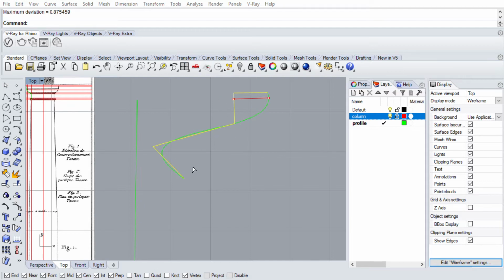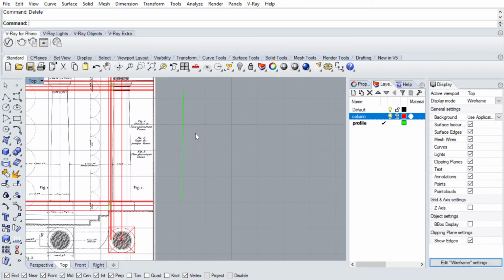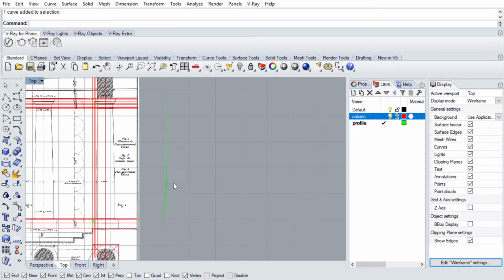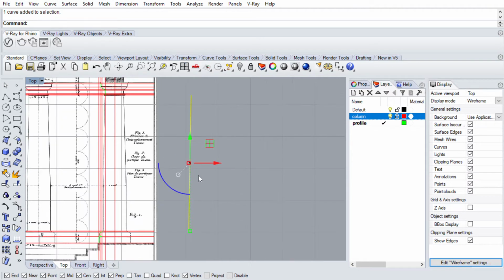If it's a first degree curve, it will be a polyline, so there will be linear interpolation between points. If it's a third degree curve, then it's going to basically have a third degree interpolation, which means it's going to take in multiple points to draw its outline. Now if I keep the point count but turn the degree to 3, you will see that the points are somewhat kept, but the interpolation somewhat affects the outline of the curve. And the rebuild tool basically enables us to increase the information on the curve and draft it more accurately to NURBS outline.